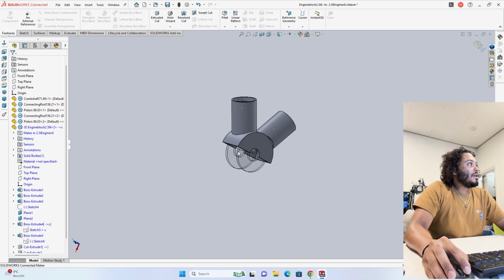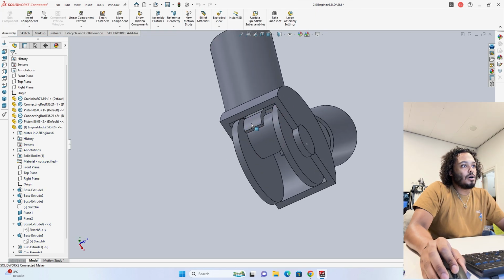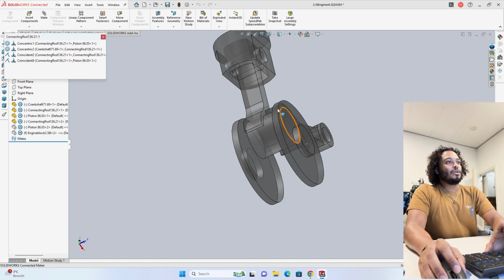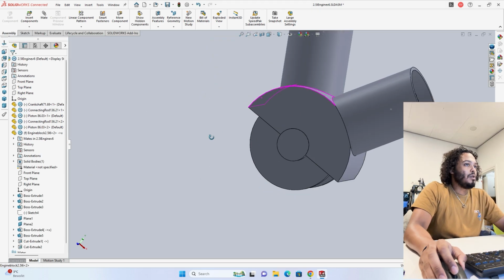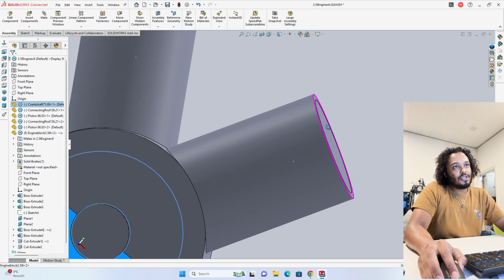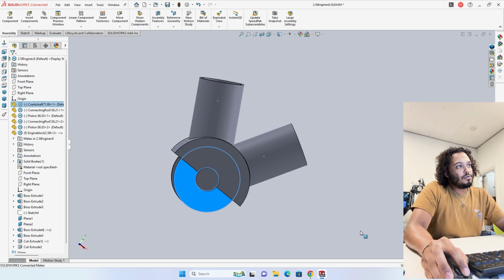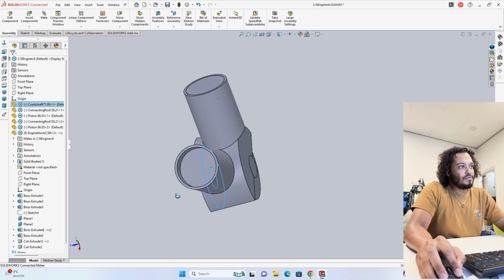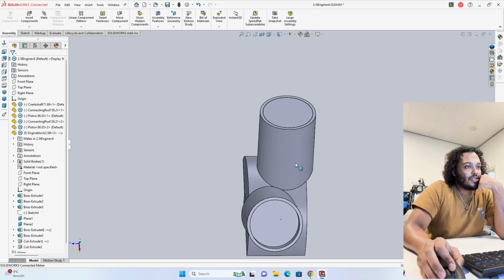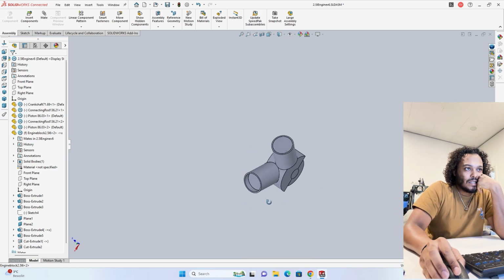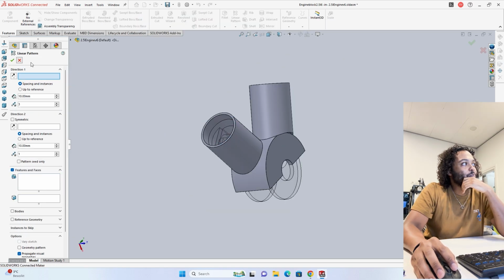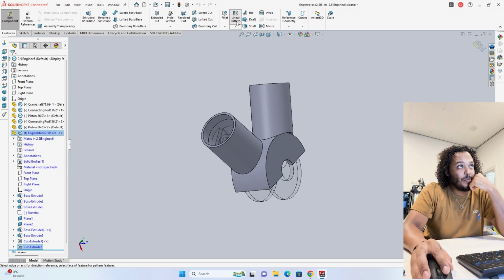And now I can go back into the connecting rod right here and take this perpendicular made out of it. Now you will be able to see that as soon as I rotate this one, it is also flush at the top dead center. So that is basically the motion of the V6 already. Now, in order to turn this into a V6, I could do a couple of things, and the way that I'm gonna go about it is by selecting linear pattern.